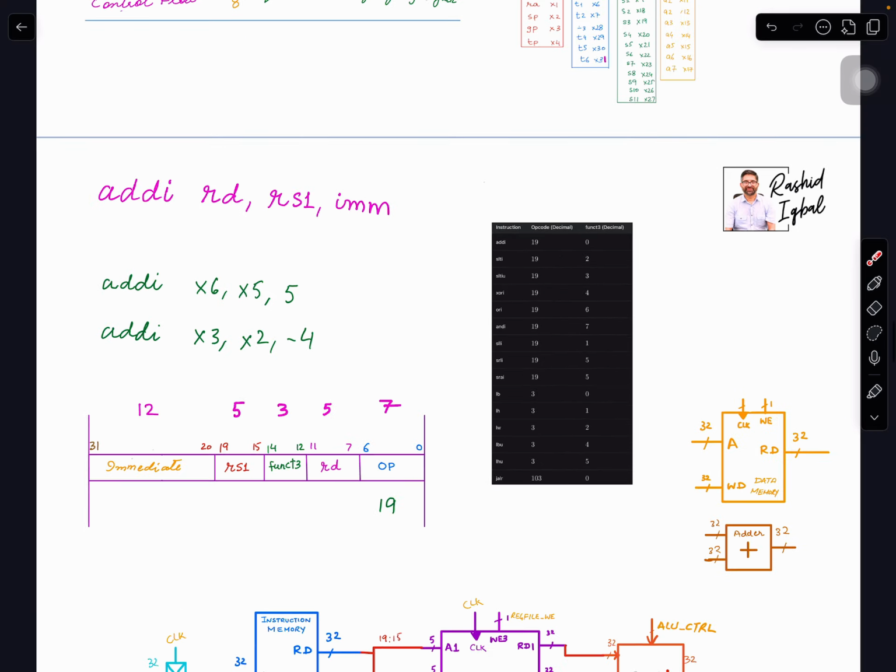So as soon as the address is available, read data is available. Keep in mind that for reading, we are not depending on the clock cycle. That's what I'm assuming right now. Once any address comes in, the corresponding value appears after a certain delay, of course. Things don't happen abruptly, but after a little bit of time, all the transistors act, and we will have this 32-bit value, which contains the binary equivalent of this, in how many bits? 0 to 31, 32 bits.